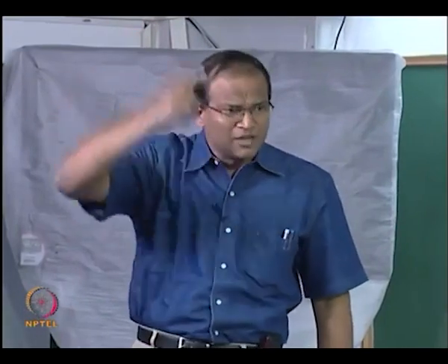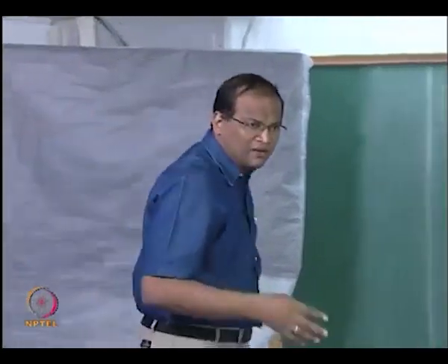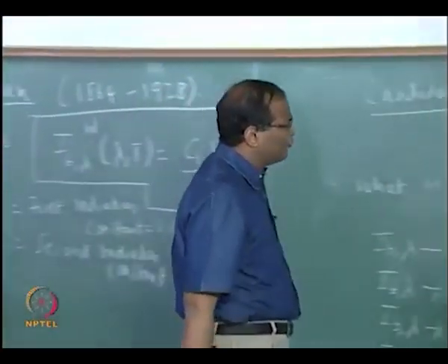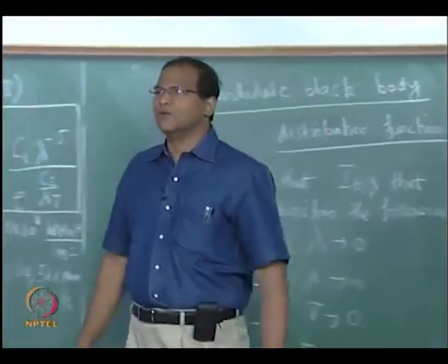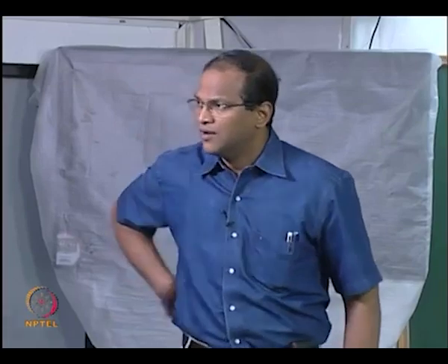Why are we so hung up on 6000 Kelvin? 6000 Kelvin is an important temperature for engineering because of the sun, it is an important thing for us. Therefore if you take the spectral distribution of I_B lambda versus lambda corresponding to a black body at 6000 Kelvin, the Wien's distribution significantly departs beyond the peak corresponding to the 6000 Kelvin. Okay, left side of the spectrum the story is fine, so it is agreeing with the experiment.